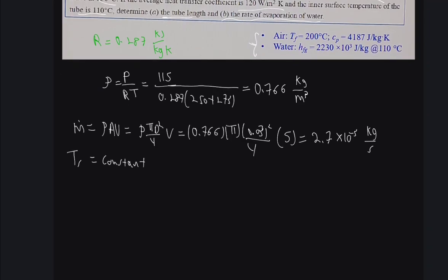And then we write down the following equation. We have ln of this dimensionless temperature term, surface temperature, exit temperature, so the natural log of this is equal to negative HA over m dot Cp. Again, this is only used when surface temperature is constant.